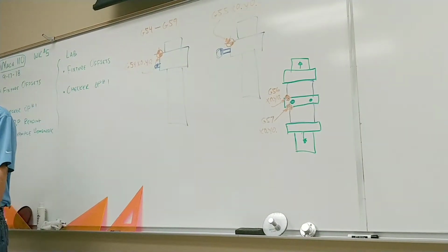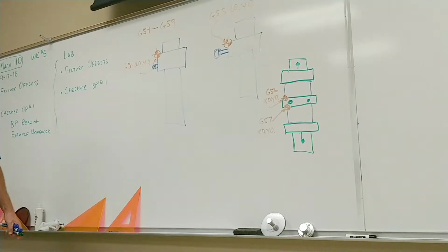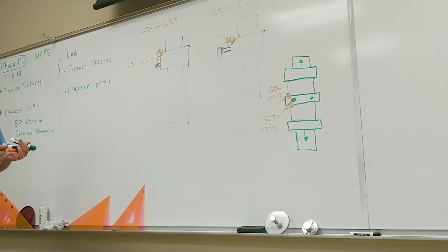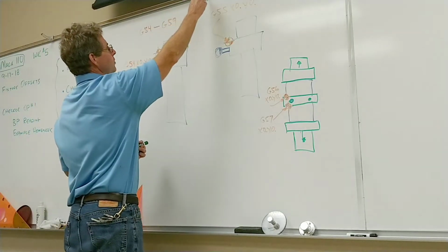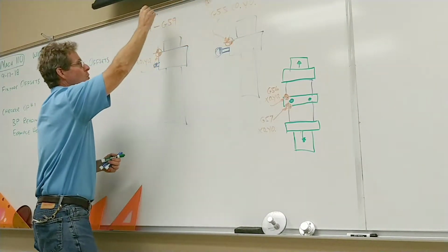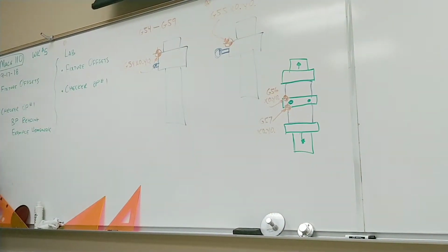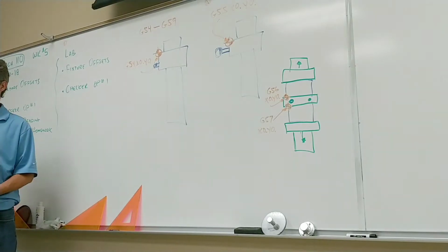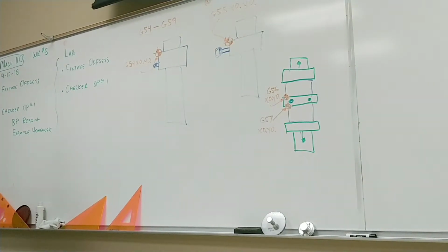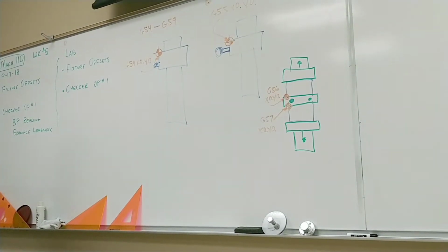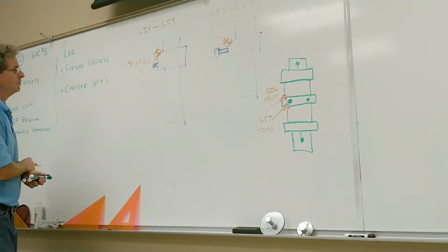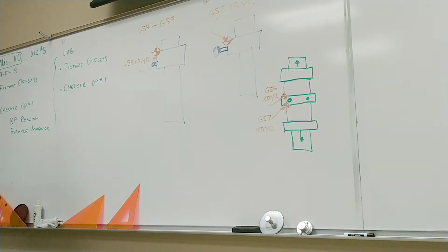What a lot of companies like to do is have some sort of system on their tables where, for example, and this is getting kind of primitive, on their table they might have 3 pins that are drilled and pressed right into the table of the machine. And then on a pallet rack, they have a series of fixture plates, nice square plates with different fixtures built on them. Well, they can take those fixture plates off and bump them up against those 3 pins. Each of those fixture plates can be pre-located. They can already have the fixture offsets loaded into the offset table of the machine and never have to set